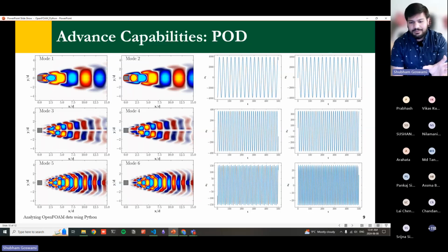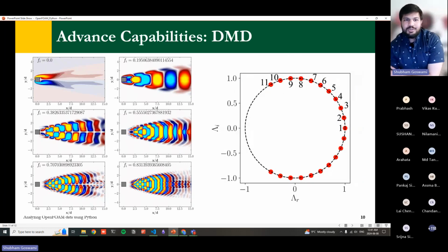It's just a matter of using matrix operations like in Python, and you can do the modal decomposition as such. You can also do dynamic mode decomposition using that data, and with enough snapshots, it would give you enough versatility for POD and DMD both. I've also used this specific workflow to perform bispectral mode decomposition and spectral proper orthogonal decomposition also.